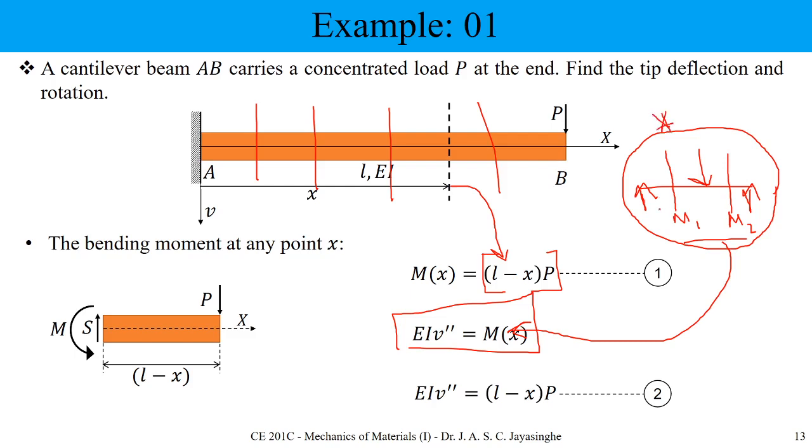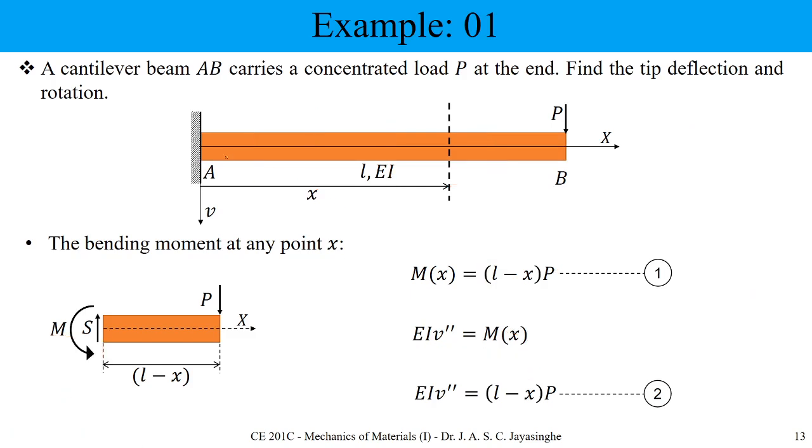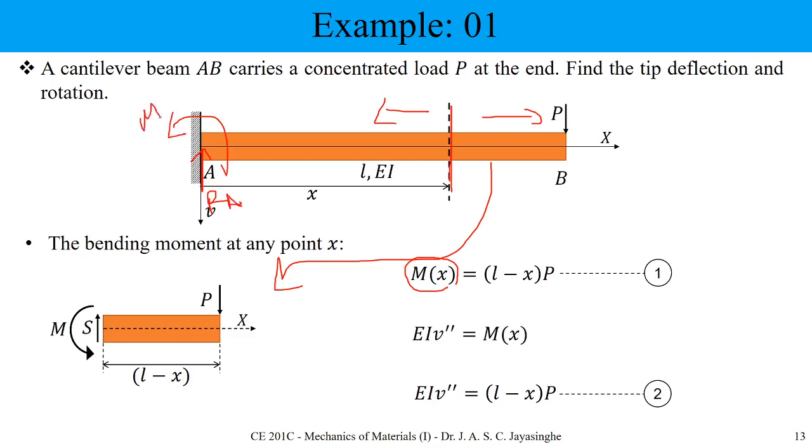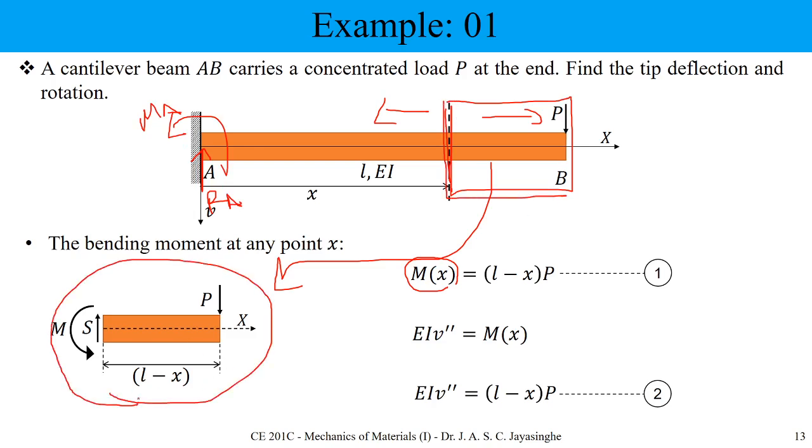We have two systems or two bending moment arrangements, so what are we going to do? Okay, in here simply we can see we can express it in one bending moment equation, and you can get the cut section from here. You can consider either this side or this side. If you consider this side, you need to find the reaction forces and bending moment. Otherwise, if you go with this section, you don't need anything. So you can just apply it, but be careful about the length. So then the length will be L minus X. Okay. So come to here, and you can get the bending moment.